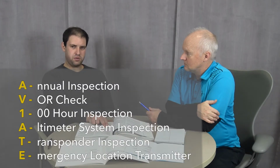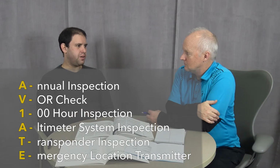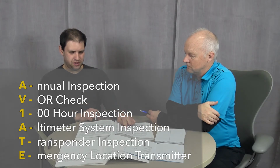We also need to have an inspection done on the emergency locator transmitter, the ELT. The Chief does have one of those. All aircraft, with some very rare exceptions, are required to have one, and that has to be inspected every 12 months. The annual is every 12 months, and the ELT is also every 12 months, so those are usually done together as well. So you have 2 that are every 24, 2 that are every 12, and then the 100-hour and the VOR check every 28 days are separate schedules.